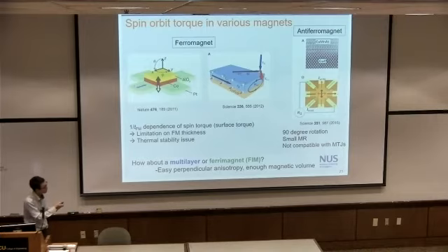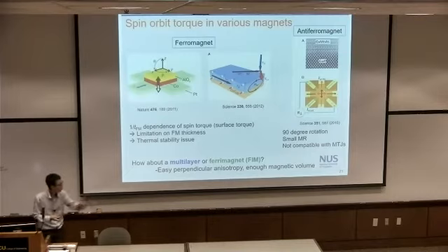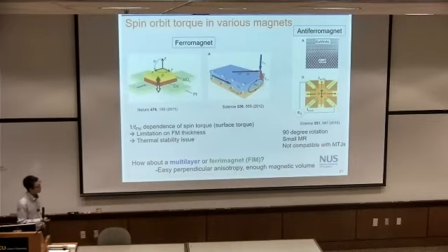If you look, by flowing the current, they can change the magnetization from red to blue, black, and black to red. So it's only 90-degree rotation, which is not really compatible with the typical MTJ reading scheme. And due to this, they use only the anisotropic magnetoresistance to read out, and the AMR value is only a few percent.